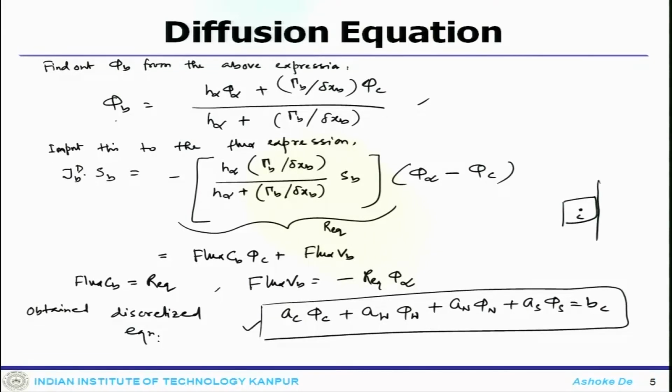This is my C element and all these boundary conditions are applied at the east face. If it had been applied to the other faces like west, north or south, those corresponding contribution terms would go away, but the differences lie in the calculation of these coefficients and also B_C.